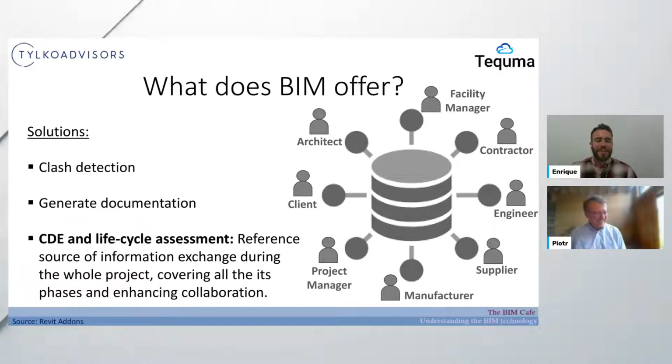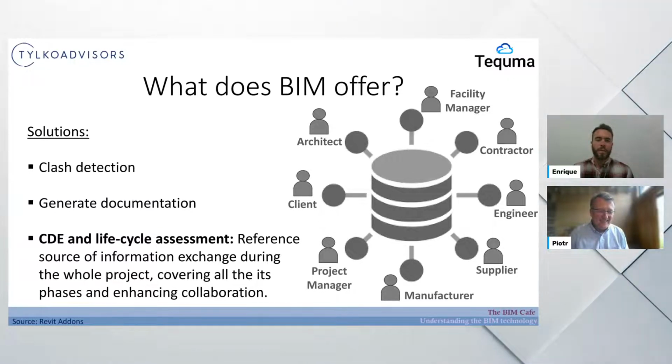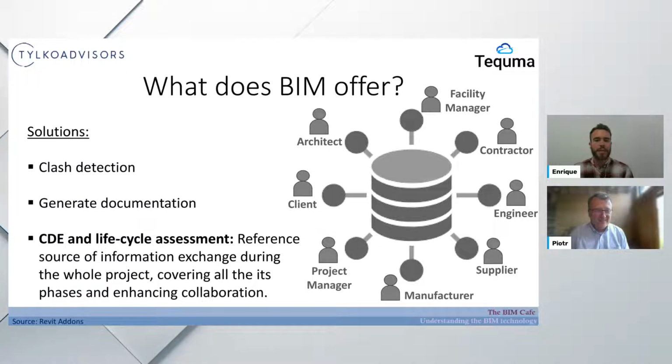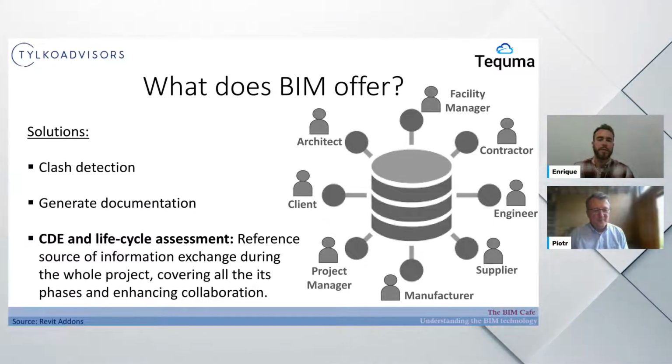This similar concept, common data environment, is, let's imagine, a cloud or a methodology which can also be BIM, where all the data is shared. If you need references, you need information, you go to the same place. It's the unique reference source for the information, where everyone, like contractor, engineer, supplier, and so on, can be part of this common data environment, or CDE.